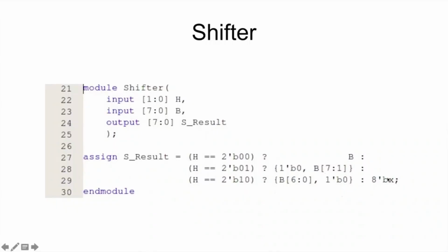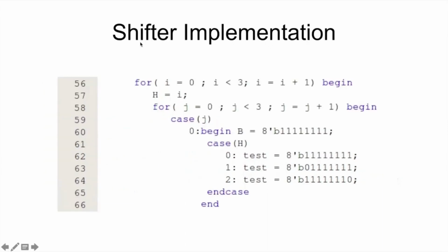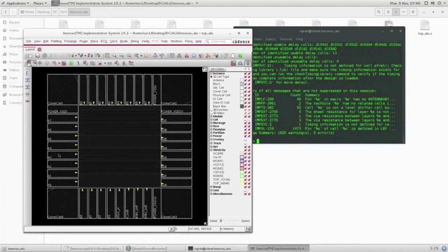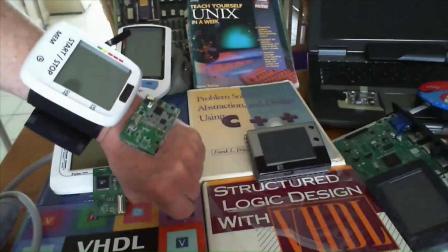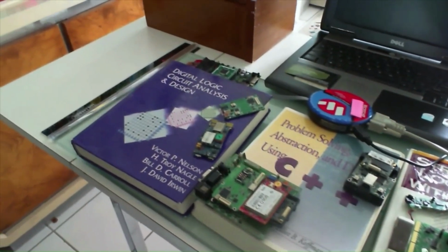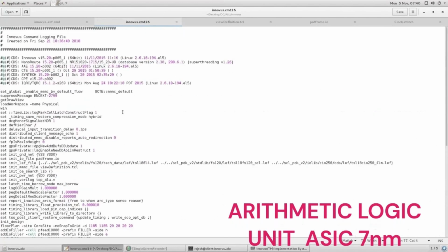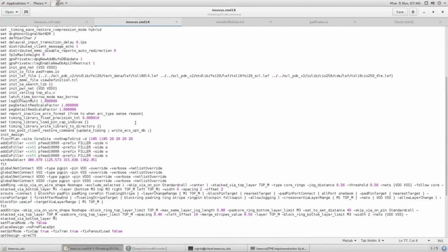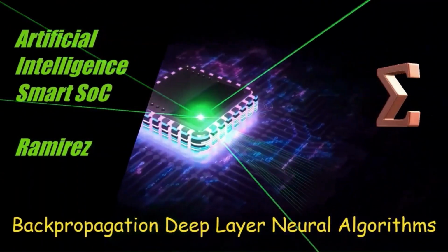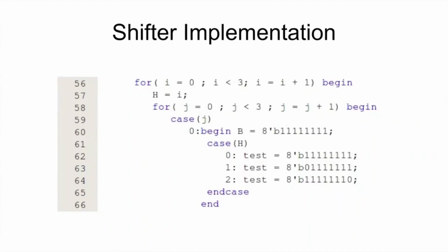This allows me to have the program route just the clock nets in the first iteration. Once it has been verified that these routes meet the clock skew objectives, the wires for these nets can be fixed during the remaining iterations. A set of timing critical nets can be routed in the second iteration after analysis has verified that these nets meet the timing objectives. The remaining nets can be routed in the third iteration without changing the wires for the clock and timing critical nets. This methodology allows high clock skew and timing objectives to be met.